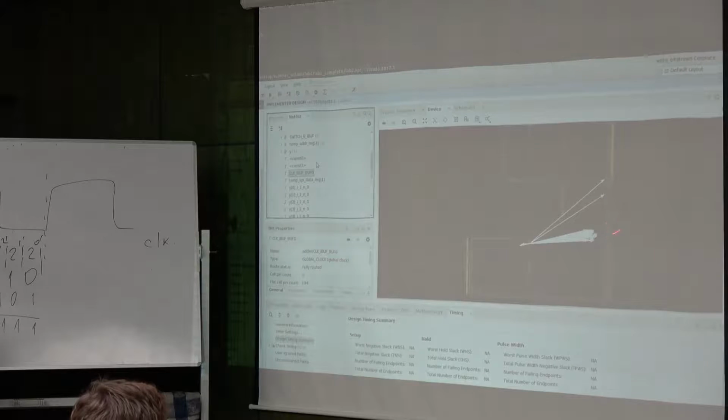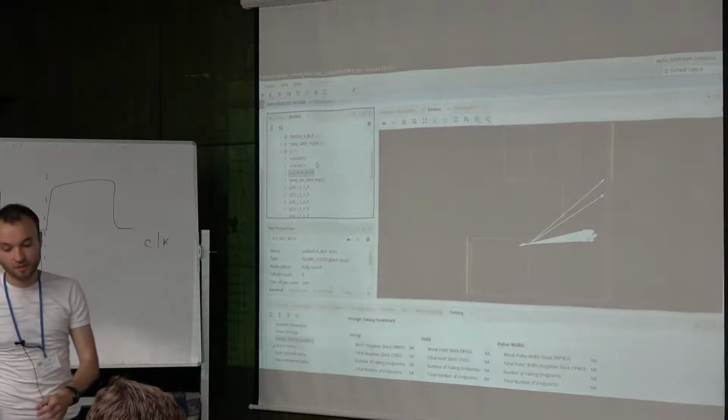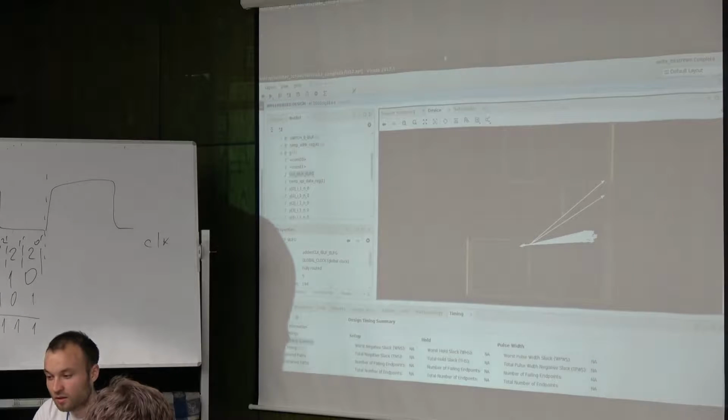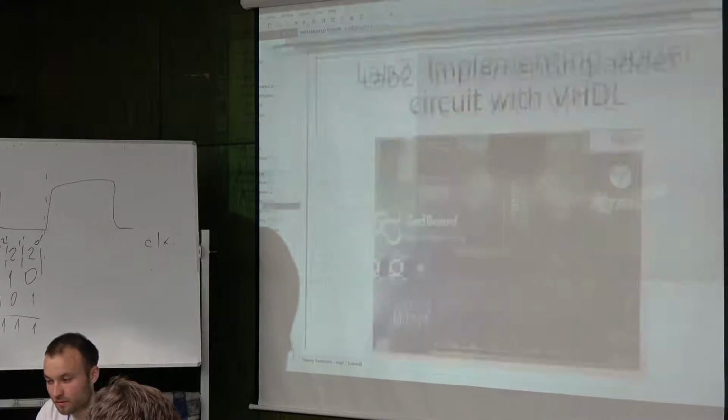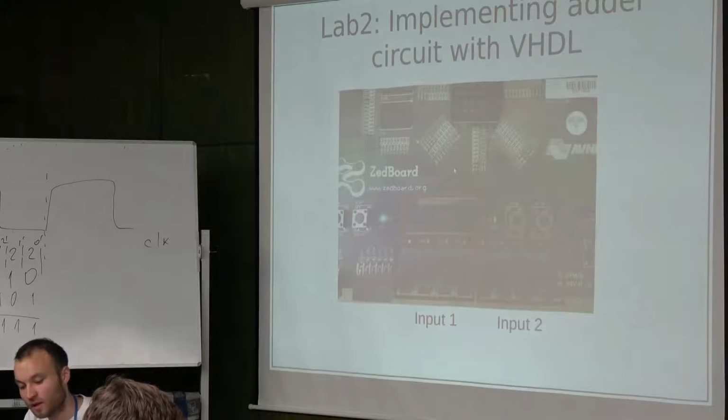So again, if you're looking for something, you first find it in the Netlist Explorer. If you want to find your adder in particular, you then highlight it here. Because in this case, the whole circuit is mostly used for visualizing the results, while the adder itself is relatively fast. Because addition for integers is just lookup tables, so we need one lookup table per bit. So it is relatively simple. Let's see if there is anything else. Yeah, I think that's it.